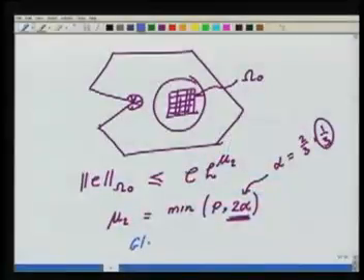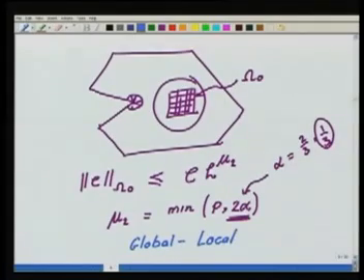and this is one of the drawbacks of what is known traditionally as global local methods, where this was traditionally ignored, that you didn't care about refining the mesh at singular points which are far away from the region of interest, but you have to do it because it directly affects my solution, the numerical solution. Okay, so this is about mesh refinement that we can use in order to get better approximation, or better quality solutions. Now what happens with the p version of the finite element solution?